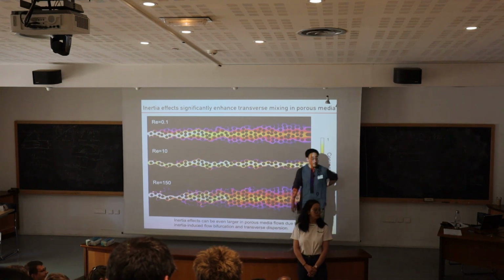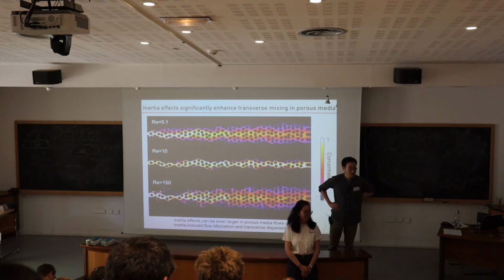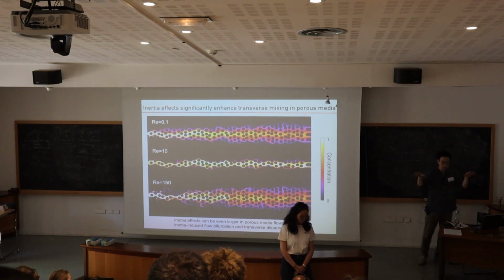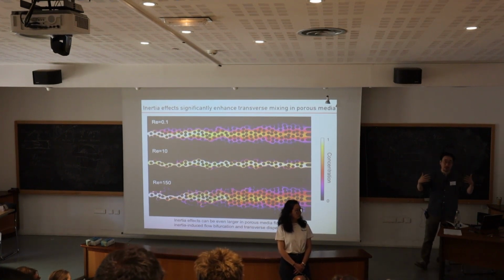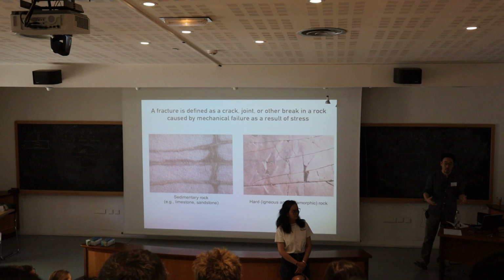John. So real quickly, I don't want to leave students with the wrong impression. Maybe I have the wrong impression, but typical infiltration rates on an annual basis are on the order of 10 centimeters a year. Typical lateral flows are on the order of a few meters. I mean, the borehole videos that I showed you, I don't know how specific Minnesota is, but you created a void. That's not a vertical flow in the borehole. If it was a natural system, you just don't have that much water. But the flow coming into the borehole, that's near the borehole definitely.